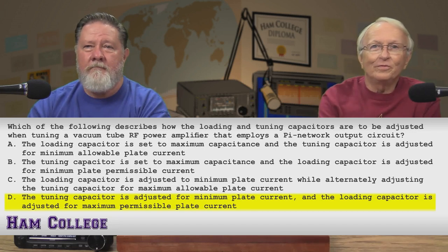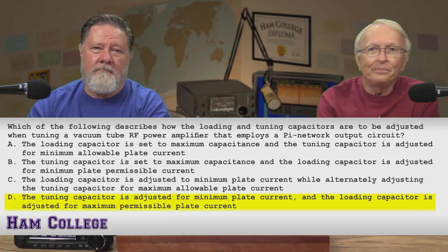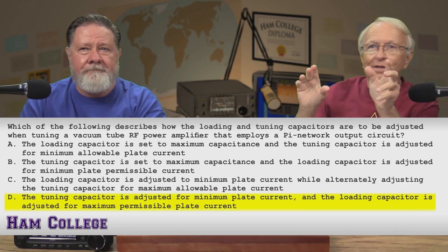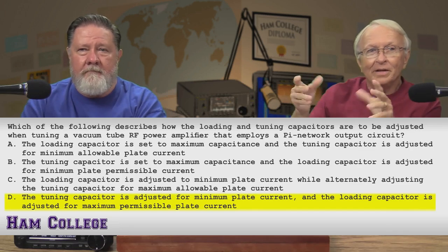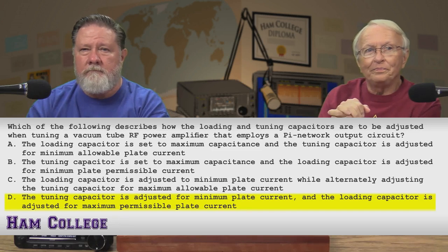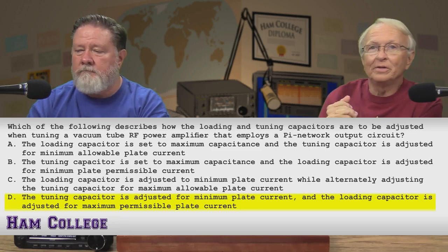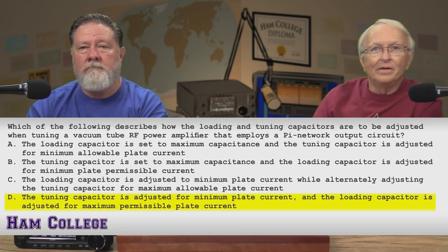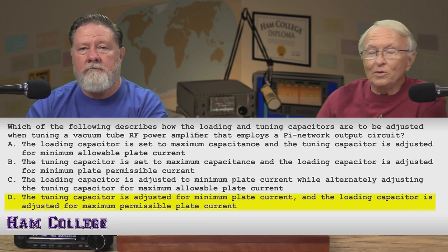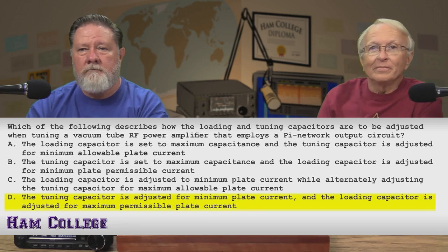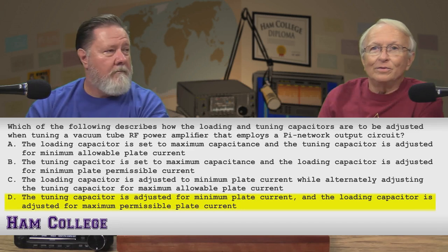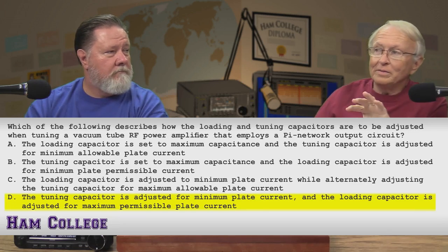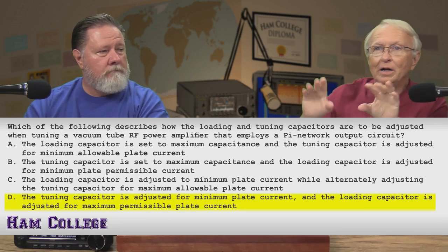But I was going to tell you before we take that break, the way I tune an FM transmitter. You got a loading and a tuning. In your linear amplifiers, most of them tube types will be similar to this. Number one, follow what the manufacturer tells you to do when adjusting one, unless you are the manufacturer. All right, so plate tuning and plate loading are the two knobs you got.